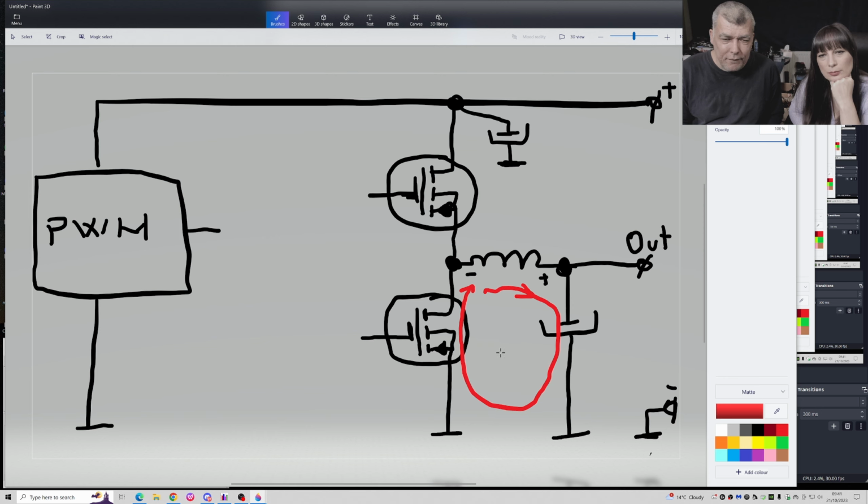Okay, and the circuit will be like that. Clear? That's how all the power supplies are these days, and they are using two MOSFETs. So every power supply from a laptop or any other device has this kind of design with two MOSFETs, instead of using a high amperage diode, which probably is expensive. Now there is one problem.